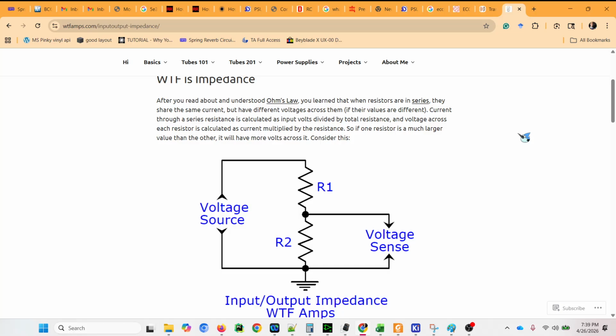Now, if you're trying to run your signal into another circuit, that circuit can just be summed up as one resistor that's going to provide a certain amount of resistance to ground. It is fighting against going to ground so it can go through all of the cool stuff the circuit is going to do for you and then get fed to the output.